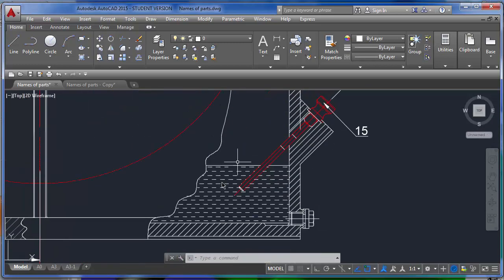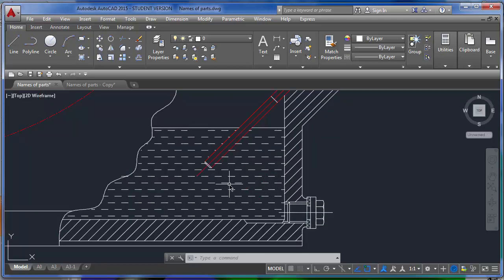This is actually the oil checker. In a standard gearbox or in another where you put engine oil or mobile, you have something like this to check the oil, how much it has. So you open it up and check the level of oil. If it's too little, you put the oil in. And this nut, actually, we open it and drain out all the oil, like burned out engine oil.